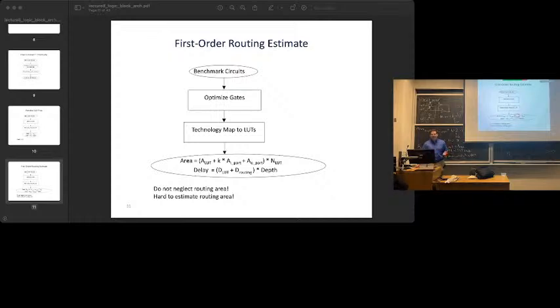The reality is that's a function of channel width and all sorts of stuff. So I can say I included it, but I just picked a number. So I'll say my number includes it, but you probably don't have a lot of faith in that because I just guessed it. My routing model isn't really going to adapt as I change the size of the lookup table, for example. Let's say that's what I'm doing. Maybe it's changing how local my routing is, and therefore the width of my channels has to change in an unexpected way. I'm not going to capture that, right?